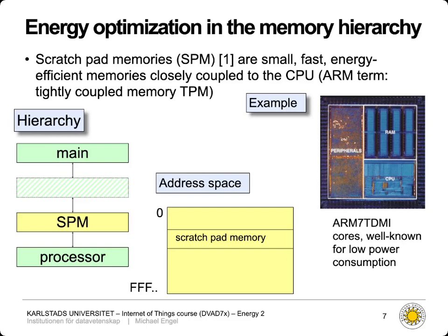So essentially, if you have the same area of chip available, a DRAM would have much higher capacity, but DRAMs have to be refreshed because they store information in a capacitor. This capacitor is slowly leaking energy, so we have to refresh the bit that's stored in each capacitor from time to time, and the SRAMs, due to their circuits, just keep their values until power is lost.